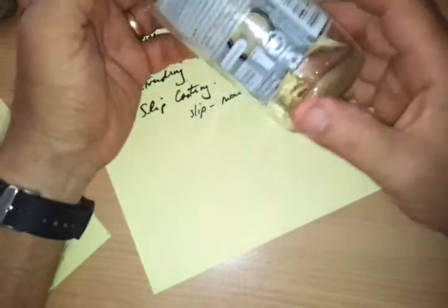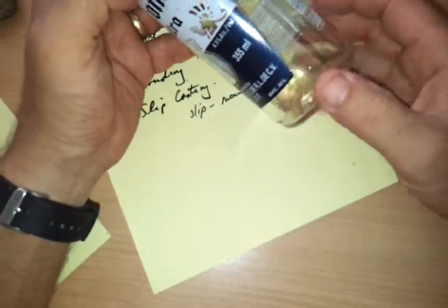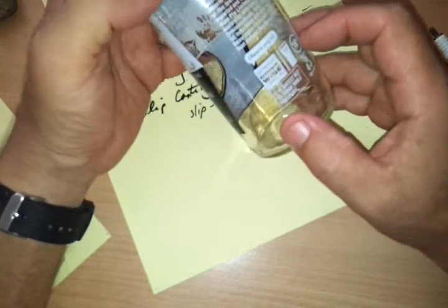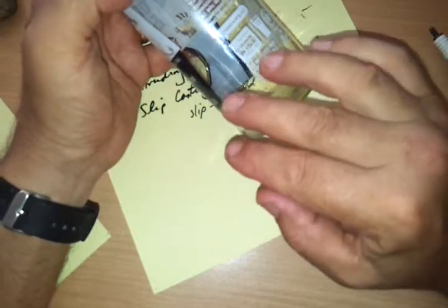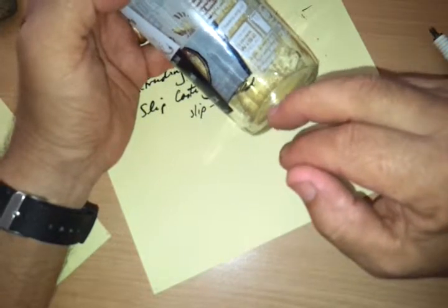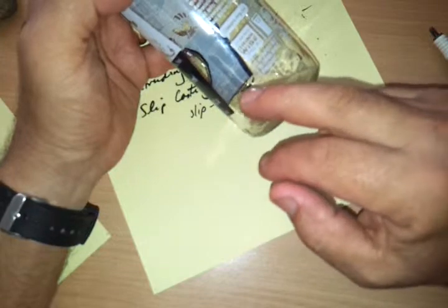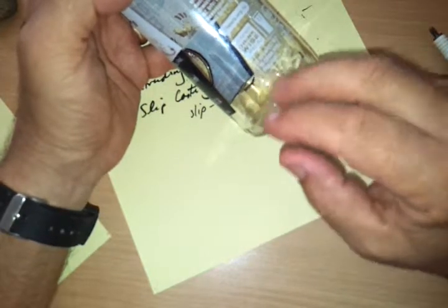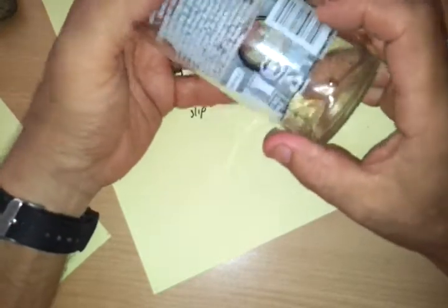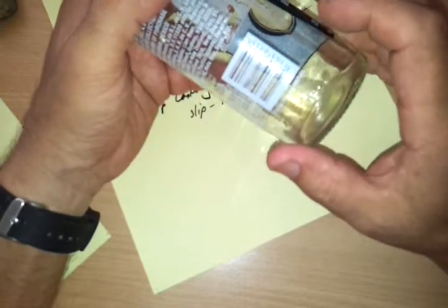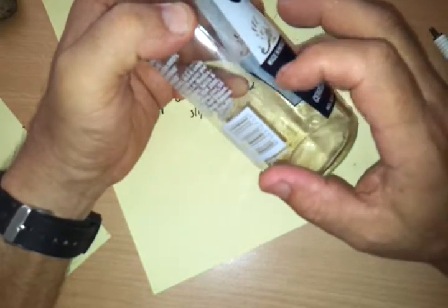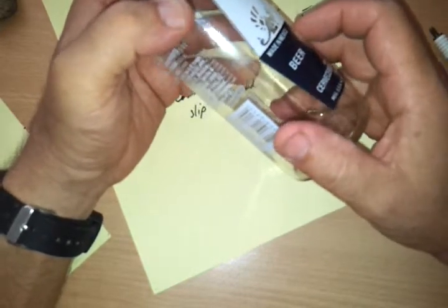The properties of glass which make it useful in the construction industry are its optical properties. It can be transparent. It's strong in compression like all ceramics and weak in tension, so it's not good as a structural material. And minute surface imperfections, sometimes called Griffith surface imperfections, can raise tension, create stress raisers that cause brittleness and fracture in glasses. So although in theory there should be quite strong bonds, very few loose electrons, and everything is stable, these small cracks, tiny little deficiencies in the material structure, make it brittle.